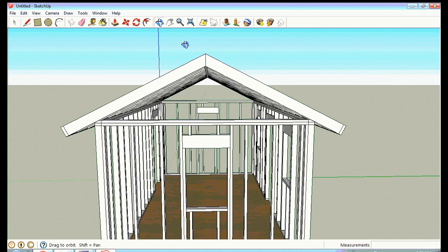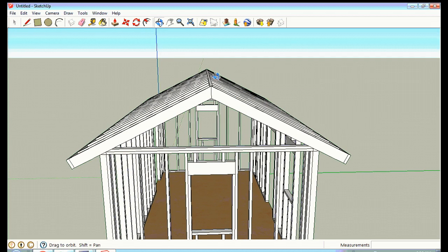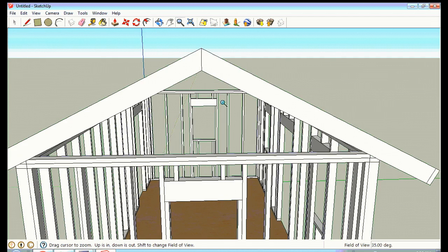But you can build end walls, and now I'll show you how to do an end wall on both of these, and then the frame will be complete once that's done, except for interior walls, and I'll show you how to do an interior wall on this too. So we're going to go ahead and do the end walls on this now. Okay, so now we're going to build the end wall that goes up to the peak here, and there really isn't an easy way to do this, but I will show you the way that I prefer to do it.